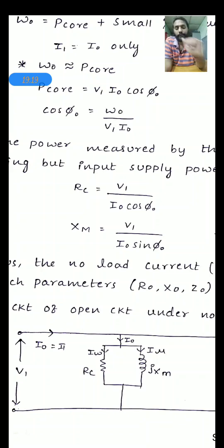It's very simple. Now the wattmeter reading can directly give the complete core losses of the transformer, because we are applying the rated voltage on the LV winding, and thus this transformer is also operating with rated flux. Once you apply the rated voltage and the rated flux, the losses are complete losses, that is, the core losses are complete core losses, not fractional values, not a percentage of the complete losses. So it can give the complete losses.